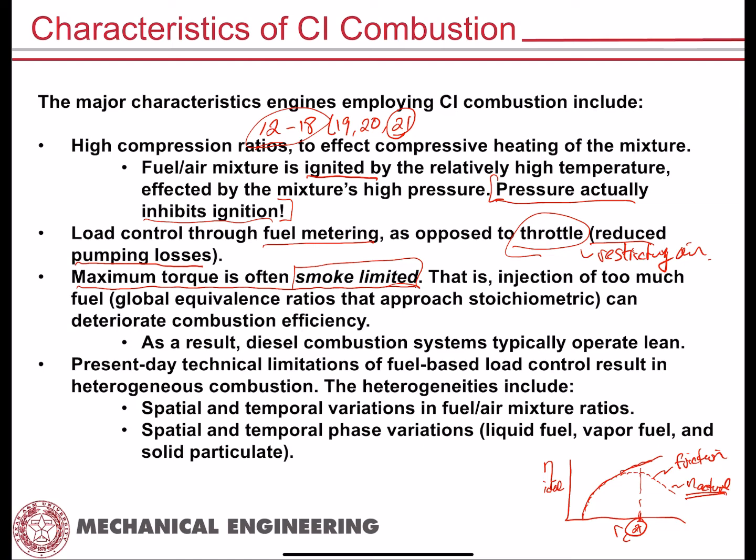So you inject that fuel into the cylinder, and you have to do a whole bunch of stuff, right? First of all, the fuel has to penetrate into the mixture, right? So remember, the air has been compressed. It's at a pressure of, say, 50 bar, could be somewhere between 20 and 50 bar, so 20 to 50 atmospheres. Go 14 psi times 50. That's the pressure in psi in the cylinder when the fuel is being injected. And so you have to, first of all, inject the fuel at a pressure that is higher than the compressed air pressure. That's number one.